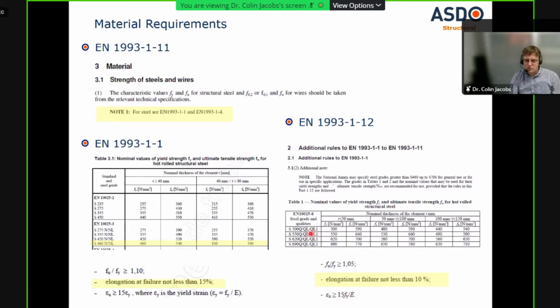Important to note that the difference in the thread stress areas means that the Indian use of root area will always be less than the stress area. Yeah? And if you calculate this out on a typical bar, like an M76 bar, you will find there's an 11% difference in the calculation of strength between the Eurocode and the Indian codes. So it's just something to bear in mind if you're looking at different systems. The Eurocode also states that you should really look at a loss of one tension component. So you should design assuming one tension component is lost and take that into account in an accidental design case.